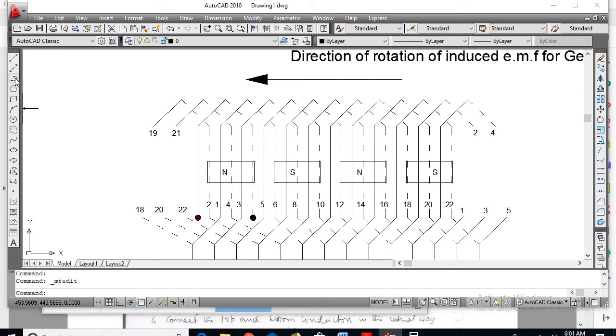So go for polyline, specify the start point, just click one point here, and now I need the next point. I have to go for width. Type W, enter. I'll select width as 10, enter, end width as 0, enter.